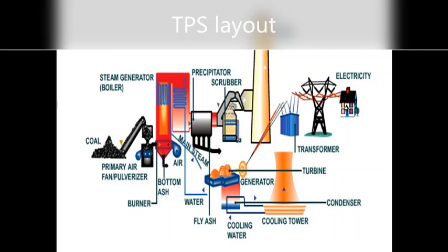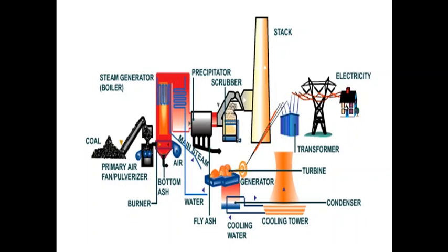Now, in a coal-fired thermal power generating plant, basically we have some fuel processing unit where coal as primary fuel and oil or gas as secondary or tertiary fuel is used, and this coal has to be received, unloaded, stacked, reclaimed and utilized as well as processed for proper burning in a steam generator or boiler.